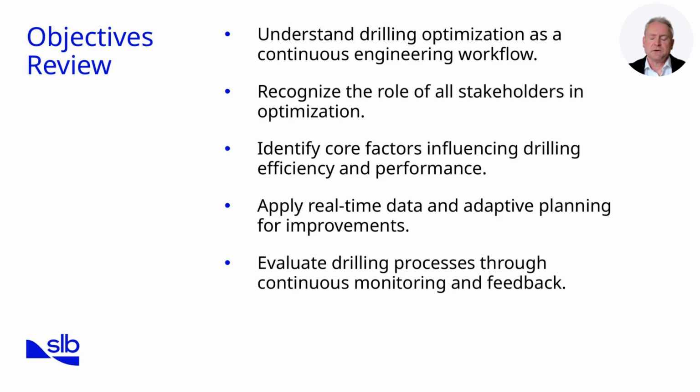Third, we set out to identify the core factors influencing drilling efficiency and performance. We've covered equipment utilization, procedures, control systems, and supervision as the critical drivers. Fourth, we looked at how to apply real-time data and adaptive planning. This is central to maintaining a living well plan and making smarter operational decisions. Finally, we focused on evaluating drilling processes through monitoring and feedback, ensuring lessons are learned and applied. Together, these objectives frame optimization as a cycle of continuous improvement.